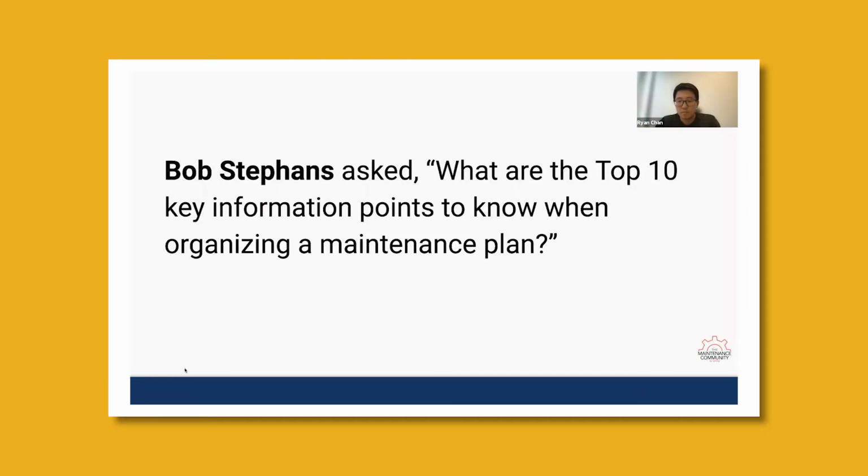Then we have to define the system asset hierarchy, location-wise and function-wise, and how that extends. That ensures all work done on the asset, whether it's failure fixing, corrective maintenance, preventive maintenance, or condition-based, whatever we are doing, is documented on a work order in a CMMS system. So we know how much it is really costing to operate and maintain that asset. Some assets you may decide to run to failure, because that's more economical. However, you need to document in the CMMS system that this asset does not have a PM plan because we have determined it's a run to failure philosophy.